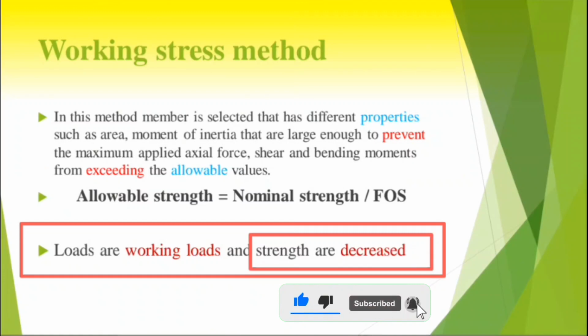And the allowable strength can be calculated from the nominal strength, which we calculate through a formula, and dividing it by the factor of safety, we get the allowable strength. For this the section will be large, and it is uneconomical for design.